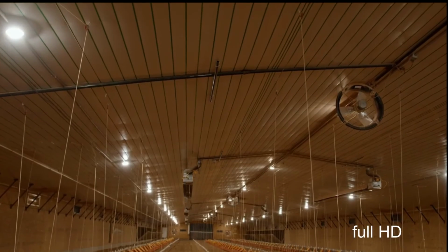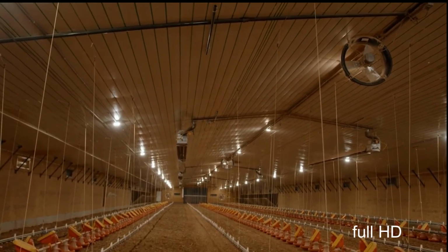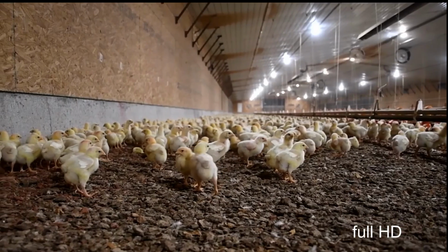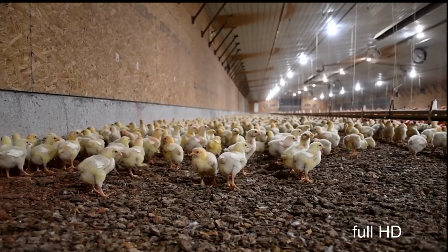Secondly, by moving that hot air off the ceiling down to the floor, we need less heat to keep our birds comfortable. We're just utilizing what we put in the house better. We also get litter drying, because not only is the air nice and hot next to the ceiling, it tends to be nice, hot, and dry. What is it going to do next to the ceiling? No, we want our hot, dry air next to the floor. So by taking that hot air off the ceiling, moving it down to floor level, we're not only warming the litter and warming our birds, we're drying the litter.